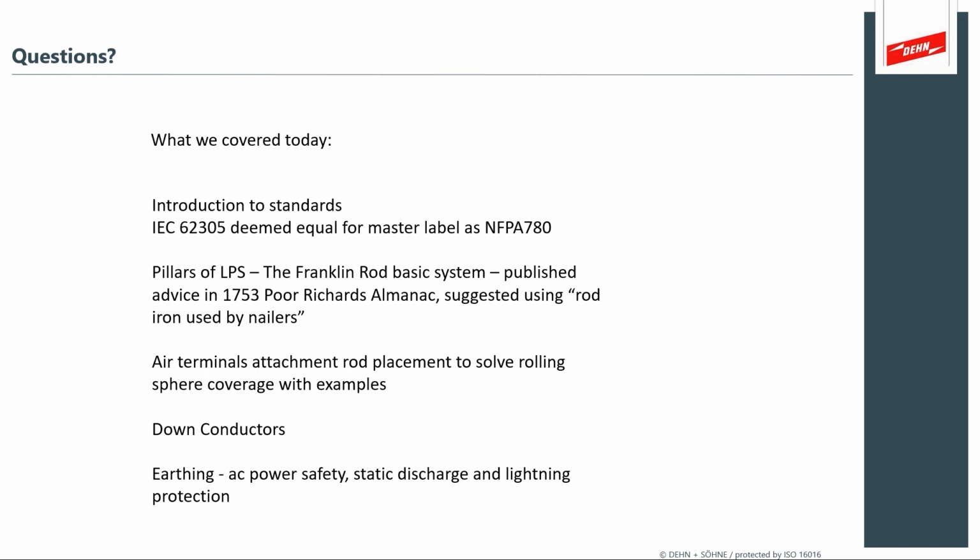But it does link back to soil resistivity and the fact that you need to maintain suitable connection to the earth. 5 meters is a reasonable estimation of the length of that conductor. Keep in mind that you also need to keep those terminals apart a certain distance, otherwise they fall within the influence of their neighbor. So it's a combination of the length of that radial and keeping it away from the other radials around it so that they remain effective.